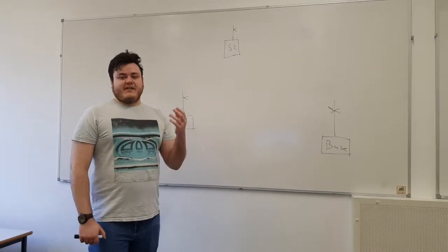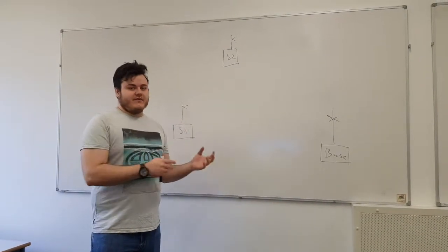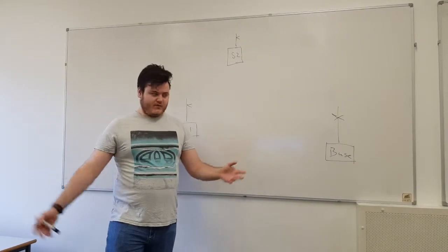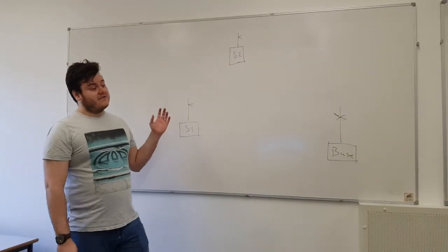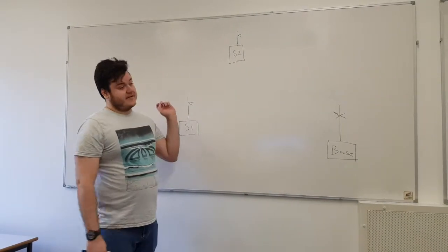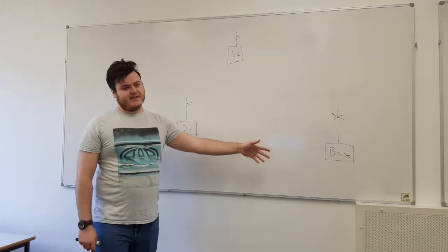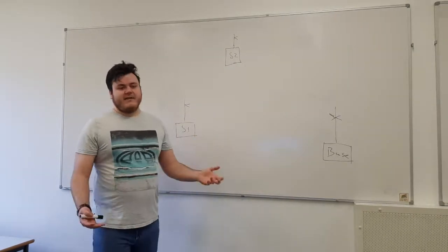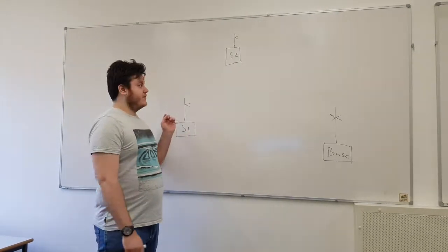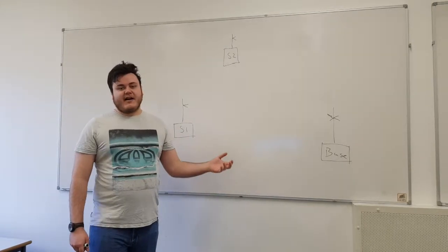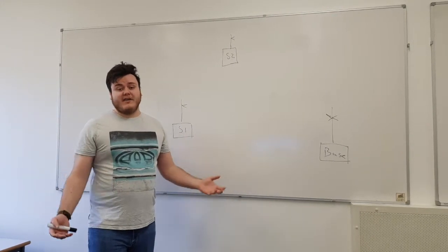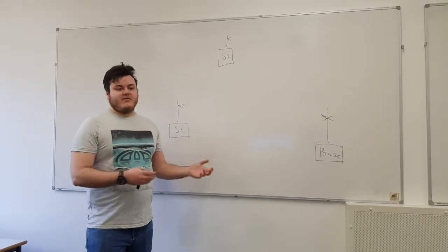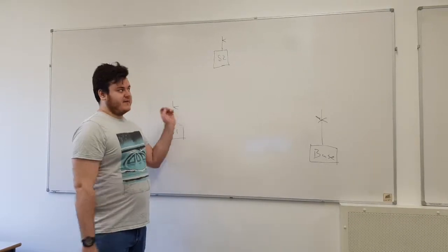And in order to get the data transferred from the individual sensor units to a base station, which then can be displayed to a user or a system, we're going to need to develop a way of transferring the data between the sensors and onto the base station. So there are different options available. We could eliminate things like wired communication, because the idea of these sensors is to have them spread out, 100 plus meters apart. With a cable, Ethernet or something like that, the signal would degrade over time and you'd require repeaters to be set between them.